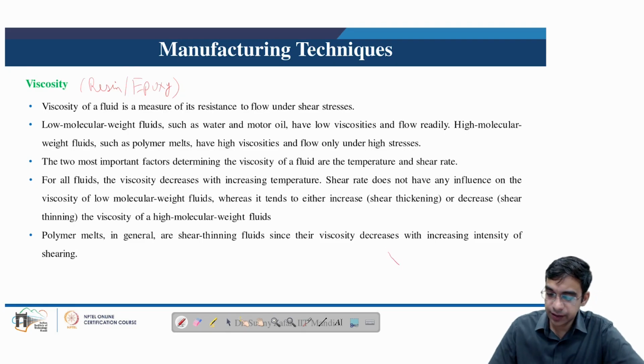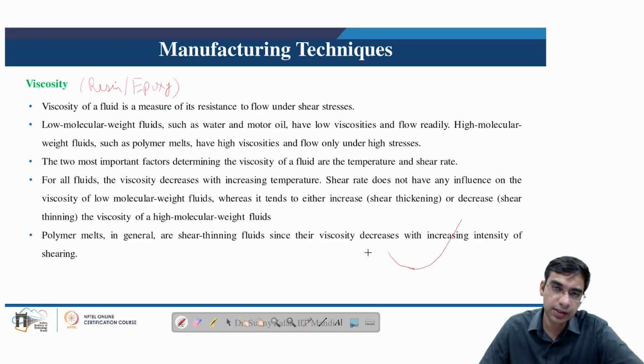It shows a decreasing trend where the increased heat energy increases the mobility of the molecules, and once gelation starts in the thermoset because of the cross-linking reaction, the viscosity goes on increasing, as we saw in the previous discussion on the behavior of epoxy to heat in the curing. So this increased viscosity as the curing proceeds needs a higher consolidation pressure so that appropriate wetting takes place, and the degree of cure also needs to be nearly equal to 1.